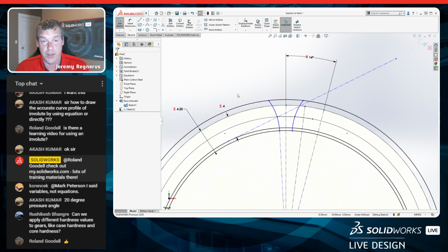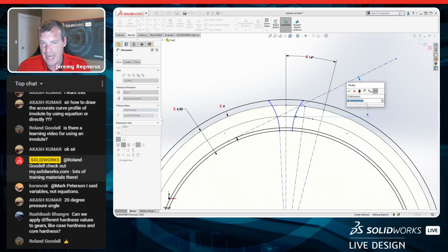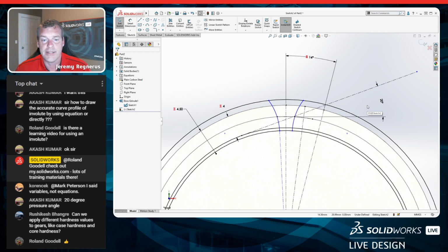Now, I'm going to show you a couple cool tricks here, so pay attention to these. A lot of people will look for a piece of sketch geometry to dimension an angle to. So for example, this construction line and this construction line, I could go in there and I could set my 20-degree attack angle basically right there.